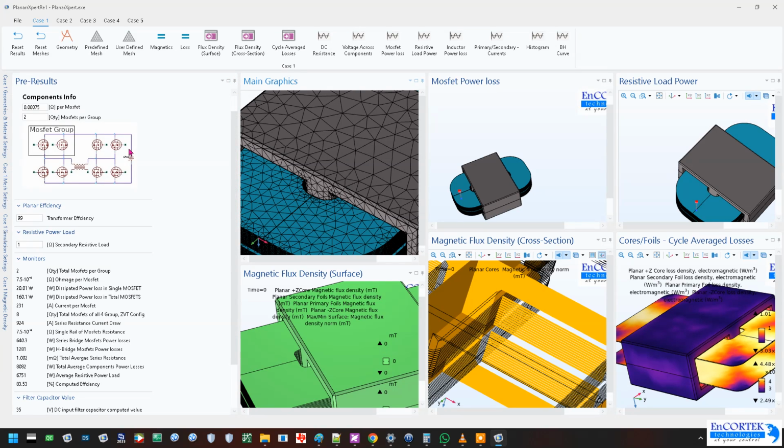We'll look at this. So now when we look at this here, the data sheet for this MOSFET is 750 micro ohms, which is an ultra low MOSFET. It's a new model MOSFET, probably about a year old release. I use two in parallel to each other, and this is a MOSFET group in parallel.